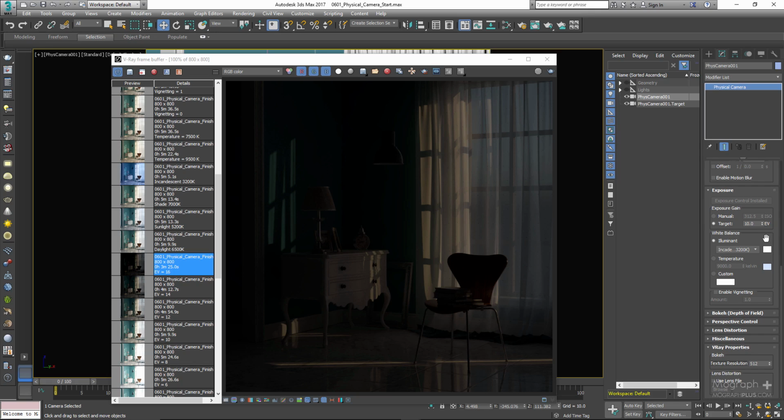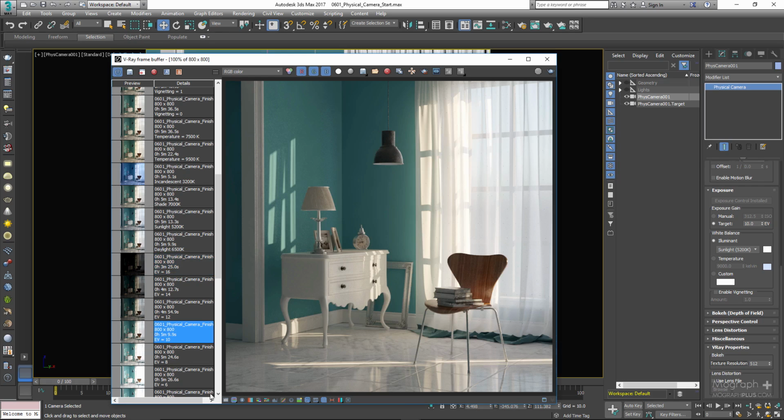If you are in natural daylight lighting, you can set the preset to a neutral daylight 6500K. If you are under very hot warm sunlight and there is some yellow color cast in the scene, you can use the sunlight 5200K preset to make the whites white again by casting out the yellow color produced by the light source. If I go to the frame buffer and load the render with EV set to 10 and also enable my correction tools and enable white balance,